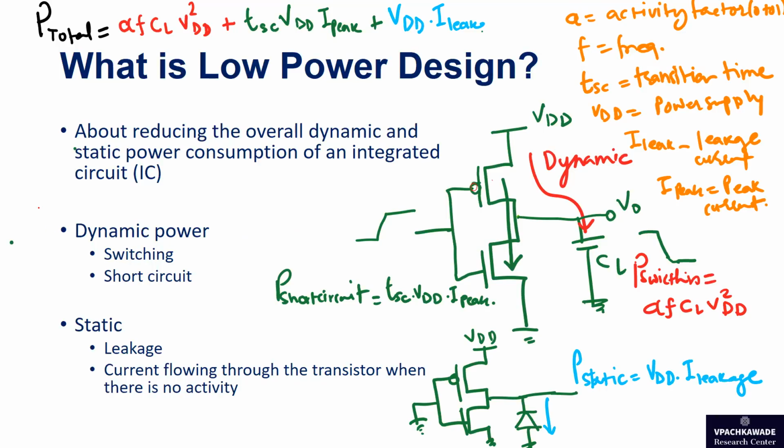The gates of the transistors are tied to each other, and you have a digital pulse switching from 0 to 1 coming as an input to this circuit. The output of this circuit is driving a capacitive load named CL, and the output is taken across this capacitor as it charges and discharges. The output is the inverted form of the input: you see logic 0 to 1 at the input, and here the output is logic 1 to 0, and the cycle continues.